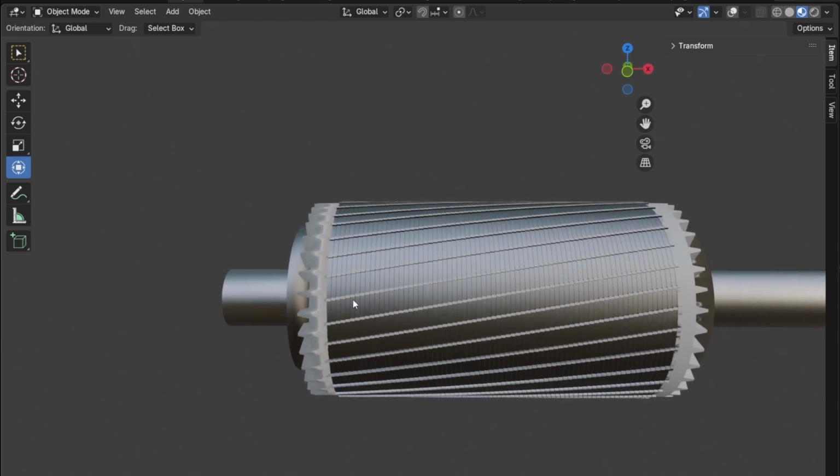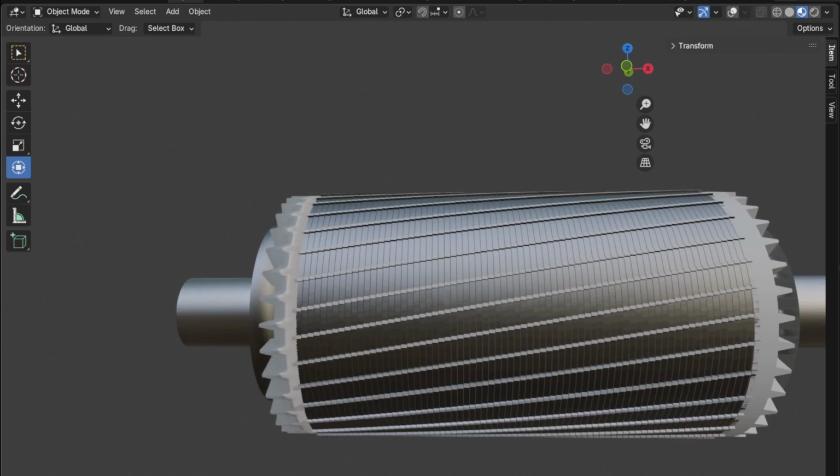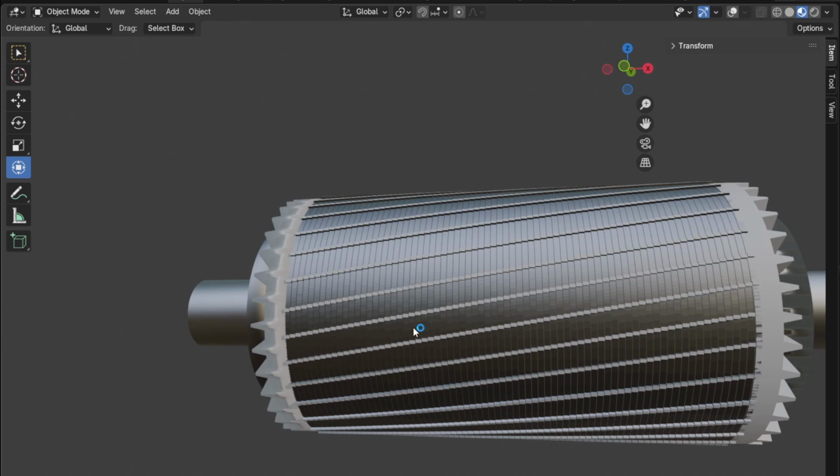And notice that these rotor bars are not completely straight. They are skewed, and that helps with the stability of the motor. It helps reduce the effect of something called cogging, where the motor would want to get stuck. It would have more magnetic resistance at one point in the rotation than others, and you end up with a turn around the perimeter of the stator that's not smooth. You have spots where it wants to stick more than others, if that makes sense. So this helps mitigate that.